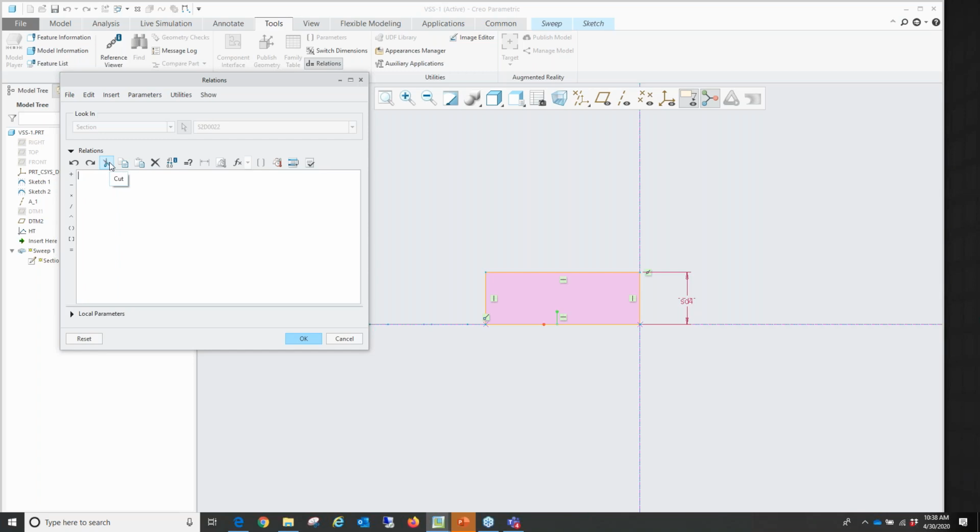So again, it's still going to be that same dimension, SD4. SD4 now is going to be equal to, and I want to say eval graph over here. And then inside brackets and inside quotes, and it can be a double or a single quote, type in the name of your graph. I called my graph HT. And then comma, again, trajpar for a trajectory parameter. And then multiply by the length of your graph. And I made my graph 100 on here. So I'm just going to add that and end it with the bracket.